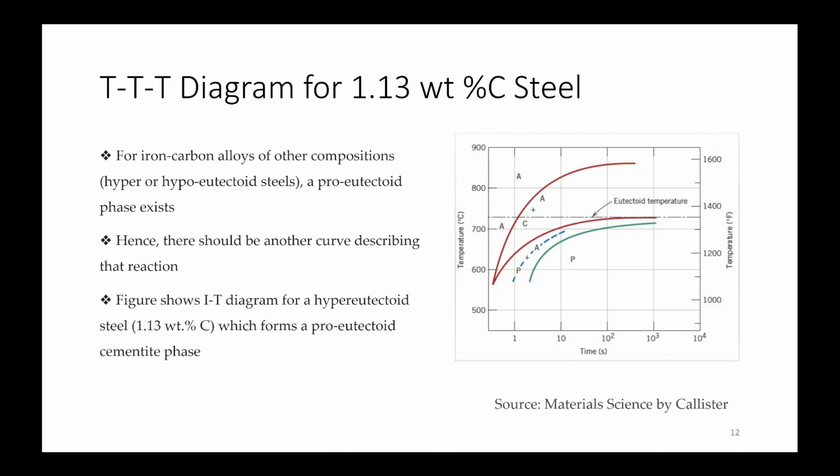The iron carbon diagram is different, so in that case when you cool your liquid iron carbon, it will cool and form graphite. So there will be all these reactions as well. In the case of cast irons, you get different reactions based on the iron carbon diagram compared to the iron cementite diagram.